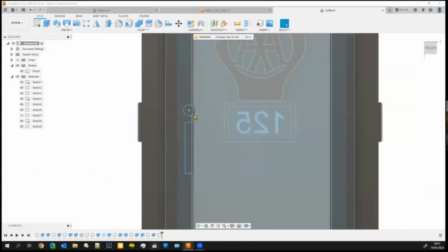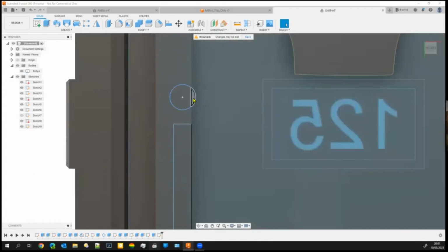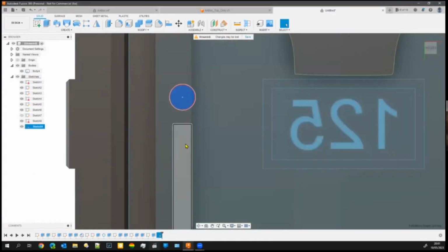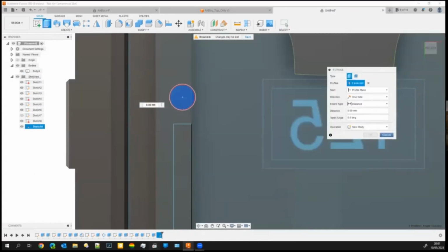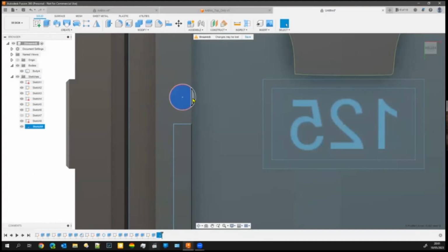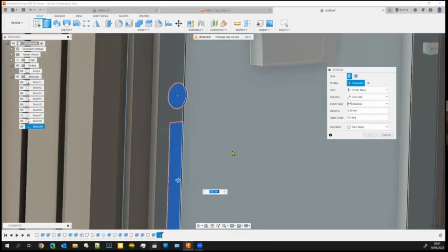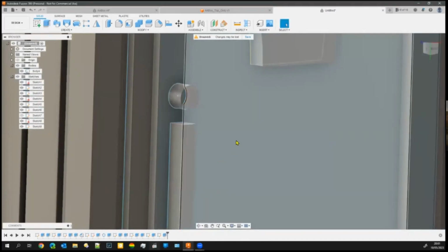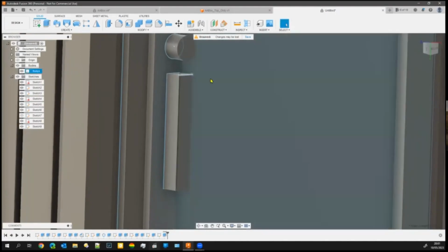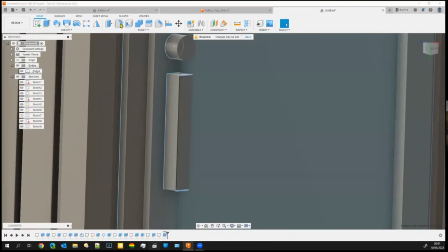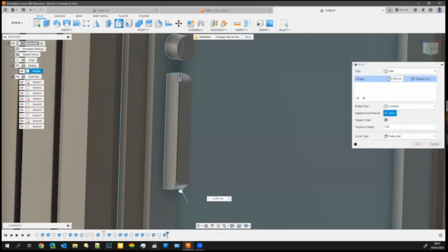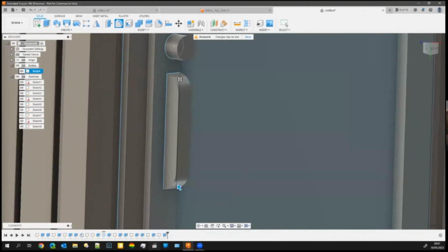Right, so you notice there we've got a slight thing there because it overlaps the edge. So we'll highlight those and extrude them out by, we highlight both of them. And that one. And extrude it out again. See which way you're going. 0.5. And on that edge, and that edge, we'll put a small fillet just to make it look a bit more like a door handle.